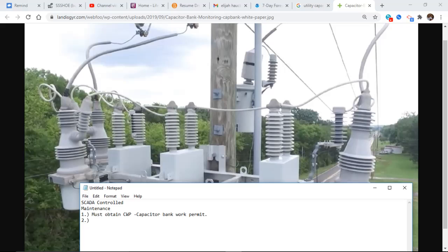Oh, sure. So they don't turn it on? Yeah, if you don't, the capacitor bank itself just thinks, I'm in everyday operation and I'm capable of turning on or off automatically. Well, we don't want that to happen while we're working on it.